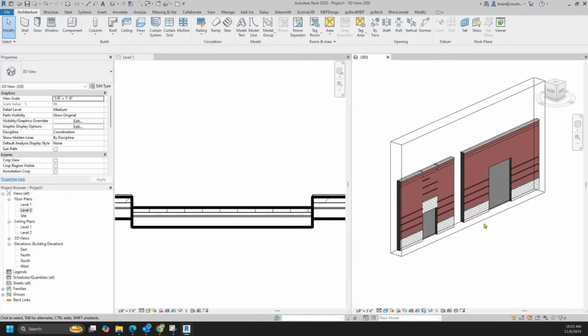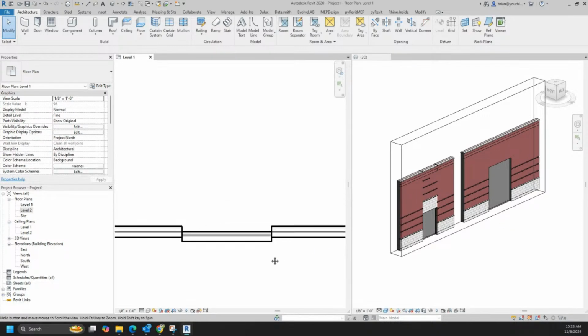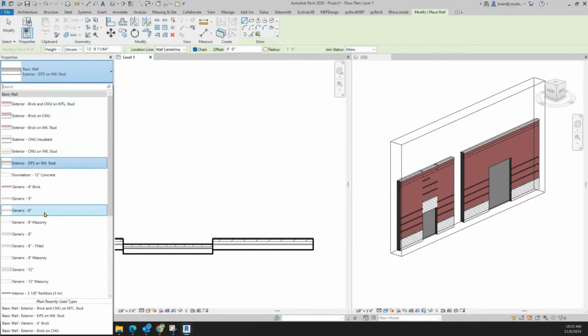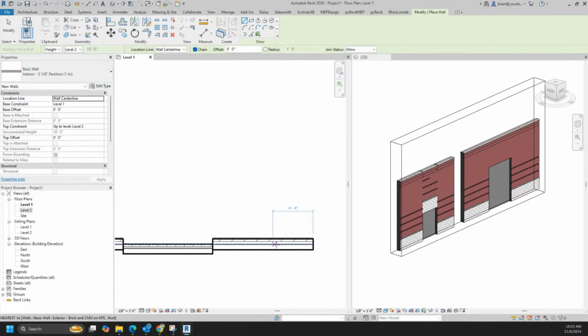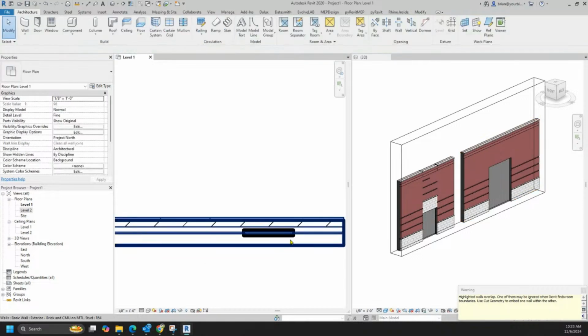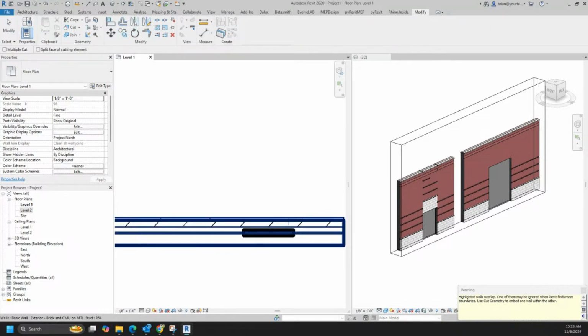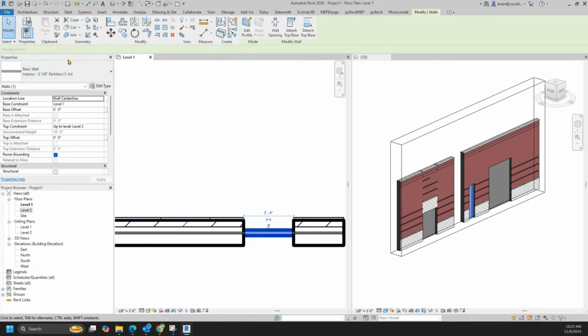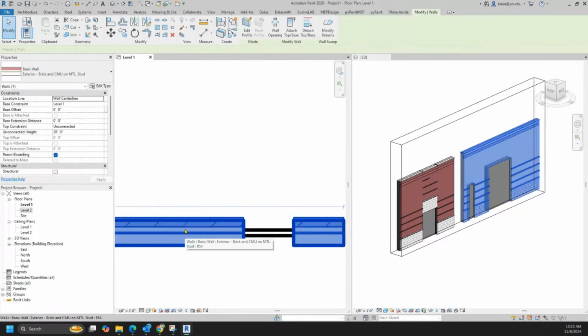And I'm just saying, what people don't know is that they can do that by simply, and it's not what you would think, because if I use a very thin wall, right, you would not think this thin wall here would cut the whole thing out if I do that cut. But watch what it does. Modify, cut this wall with that object, and it cuts all the way through it. And see, that's where I'm saying, if this guy had a real stud, what does this one say? This one says this is brick on a metal stud.